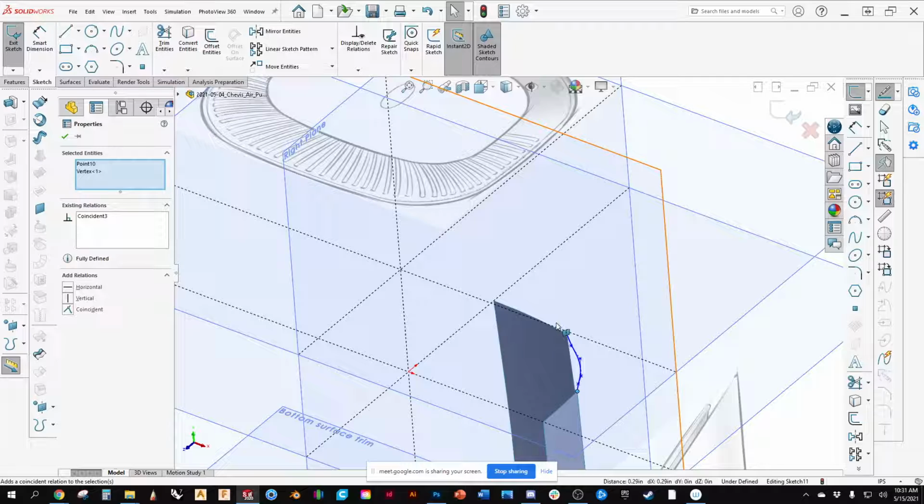If you think G3 or G2 is going to be good enough, keeping in mind that G1 is positional, so it could have an angle. G2 is tangential. G3 is curvature continuous. Keeping in mind that with G2, you're going to get that radius where it just kind of rolls over, and you're going to see where the highlight starts and stops during that transition. Well, for this, I want a nice, smooth, seamless thing because that's what makes this look soft and clean.